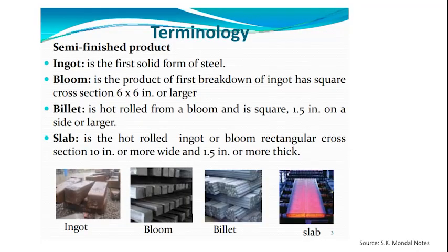These are some terminologies that you have to know: ingot, bloom, billet, slab. How do we get ingot, bloom, billet, slab? Can anyone tell, what is the process to get an ingot? When you cast a product, you directly get it in the form of ingots, blooms, billets or slabs. Even in forming processes, these are the standard semi-finished products through which you turn your molten metal.